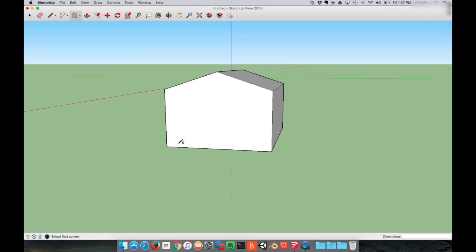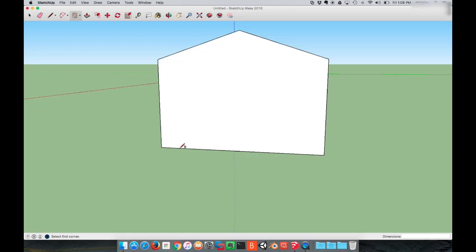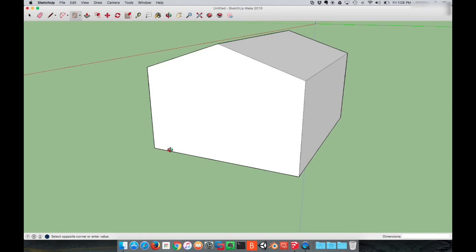I use my rectangle tool. It's not giving me the button I need. Orbit around again. Sometimes you just have to change the perspective. Great tool for teaching kids about perspective. Get on the edge there. Draw a little door. Hit spacebar to get my select tool, select that area, it's a separate face, and hit my delete or backspace key to delete it.